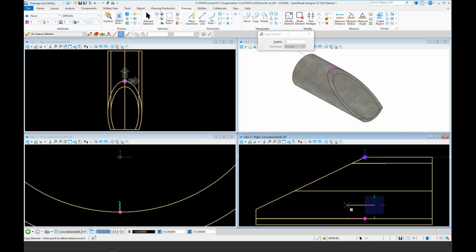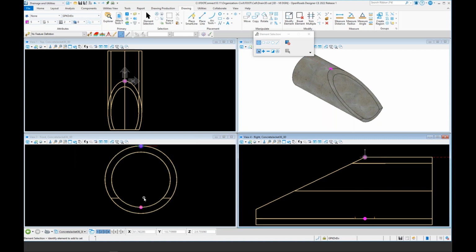And since I moved 6 inches that way, I want to do 1 foot off in this direction so that the two of them will be 6 inches offset from the center line of the connecting jacket. So, all right, now that we've got that done, everything is set up so that I can start doing the modeling of the actual jacket.